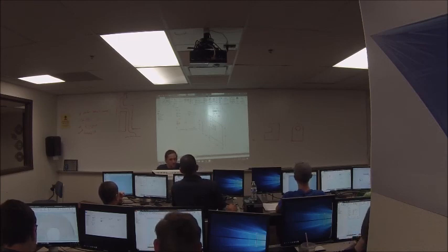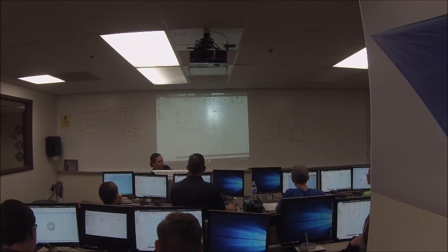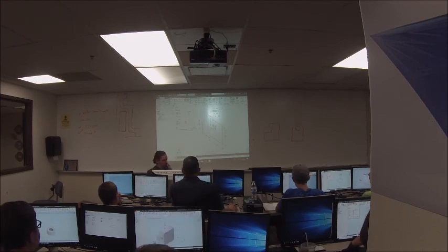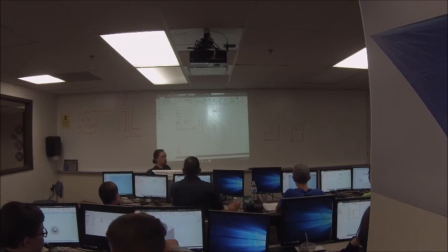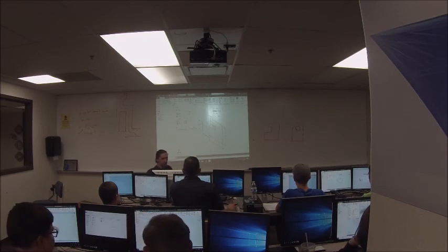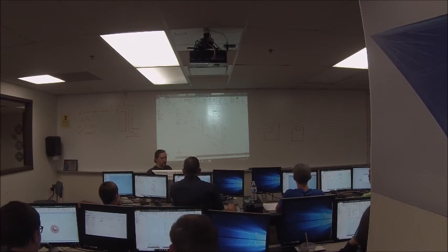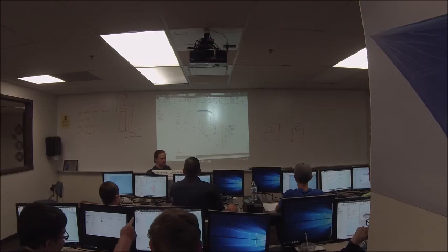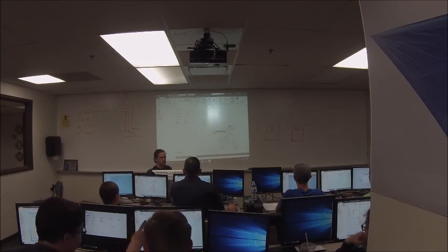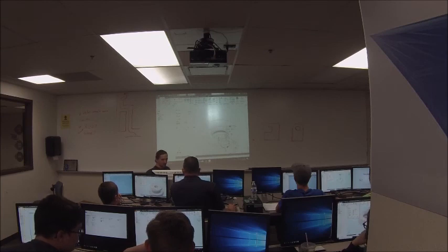But so you can see over here, there's a profile button, right? That's for selecting your region. There's an axis button. So go ahead and click your region, okay? And then select the axis button, and then click your line. And all of a sudden, bam, it will revolve part. Then you can click the OK button. And it will revolve part.